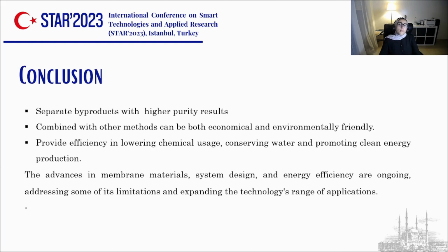Finally, to summarize, ED is used to separate byproducts with high quality, high purity results. Combined with other methods, it can be both economical and environmentally friendly. It provides efficiency in lowering chemical usage, conserving water, and promoting clean energy production. The advances in membrane material, system design, and energy efficiency are ongoing, addressing some of its limitations and expanding the technology's range of application.